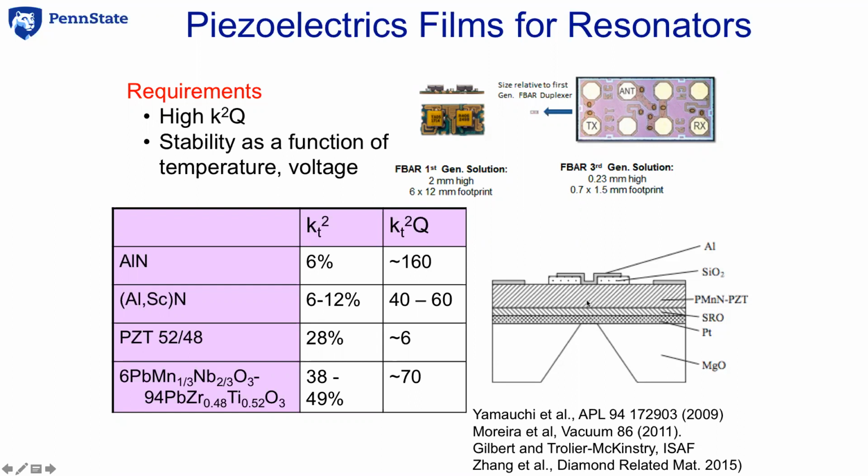And this vibrates in the thickness mode. Because all materials which are piezoelectric convert between electrical and mechanical energies, as I undergo a mechanical resonance, there's always an electrical signature of that mechanical resonance, and we use those changes in the electrical impedance to make extremely small resonators.